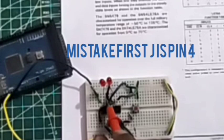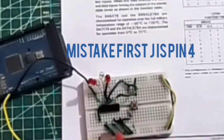You can see this thing. This is the clock for the first flip flop. This is the preset, this is clear, active low, so we make them high. And this is K and this is J for the first flip flop. Pin number 4 is ground. Pin number 5 is the positive pin.